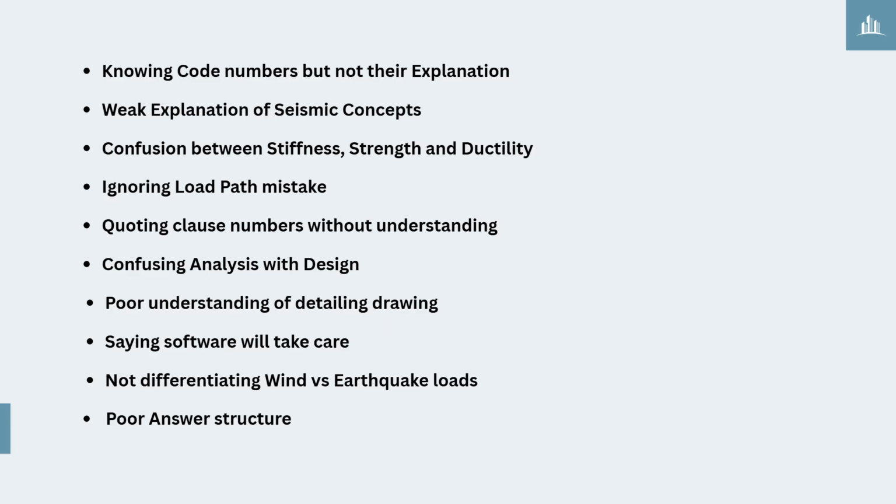You can say that firstly, the loads act on the slab and are transferred to the beam through bending moments, and the beam transfers these loads to the column as axial forces, and then the column carries the loads down to the foundation, which finally transfers them to the soil. This is the proper explanation of the concept. A continuous and clear path is essential for safe and efficient structural behavior.